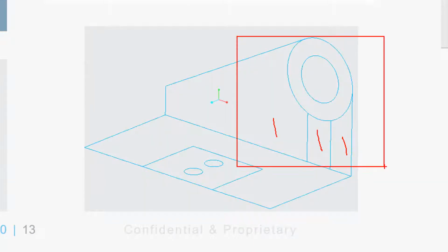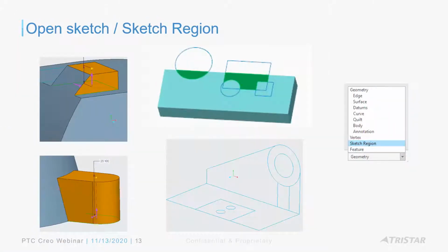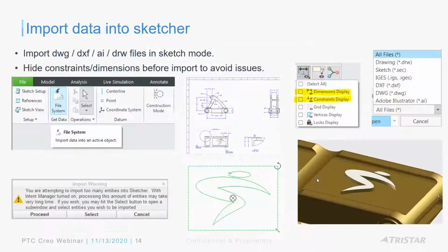I can just drag a window and then select multiple regions and then extrude them, right? So a different workflow, maybe if you use skeletons and multiple sketches, right? It's a good practice not to obviously have a complicated sketch, right? You typically do feature-based modeling, but it will be helpful, I think, where you no longer have to spend as much time as you used to trimming those sketches and curves like before, right?